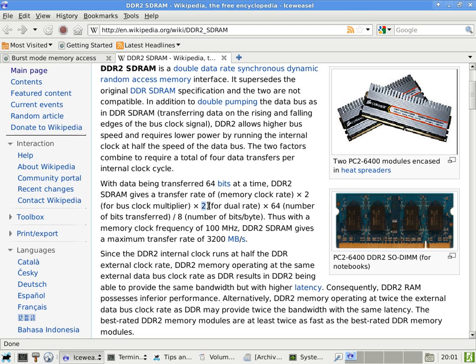there's no signal to tell both the processor and the RAM this is the time. There's no edge. There's nothing that can be observed. So this is purely based on the internal timing mechanism of both ends to say that this is the right time to latch out the data, and this is also the right time to sample. So that timing is really, really critical with DDR3 already the way it is.